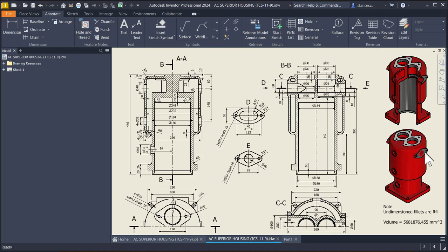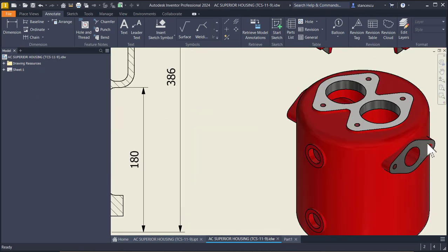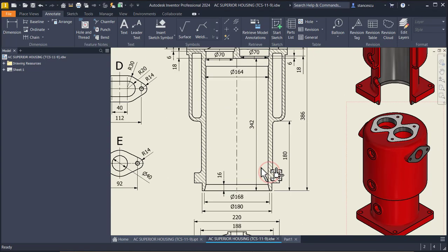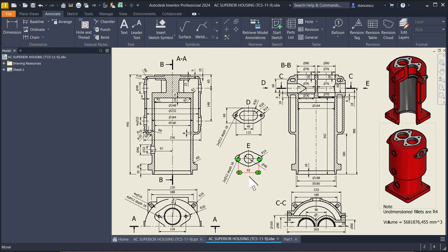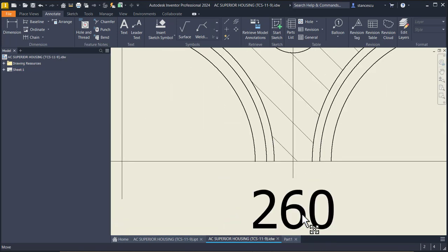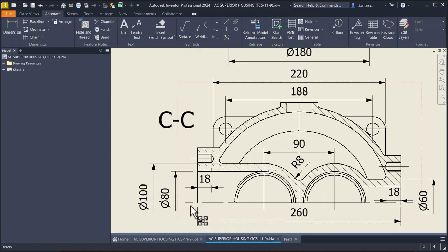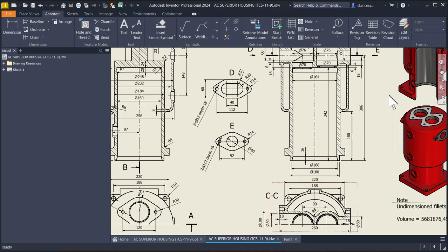Now I place this external volume, which has dimensions here, and with the dimension of 260, you see here, 260 between the two. If I don't have any other prescription, I understand that these are symmetrical placed about this plane or axis.